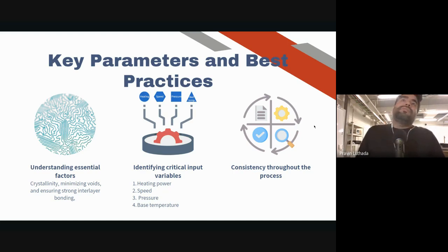This is one of the myths, that people want to run thermoplastic processes fast. I've talked to a lot of experts, and what I've understood is that there is only a certain speed at which you get diffusion. You can't hasten that process by just going faster and melting more. You're just going to degrade the plastic even more. So you would definitely not want to go really fast.